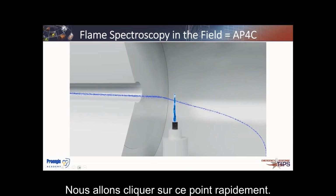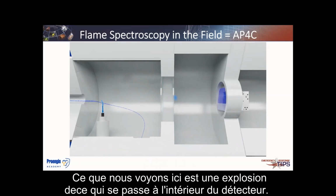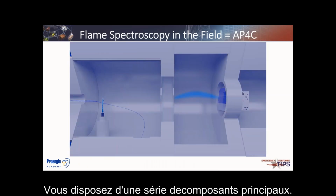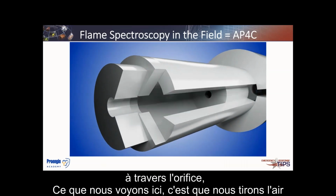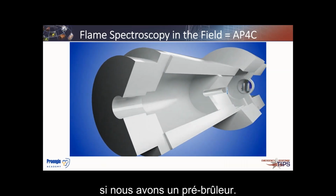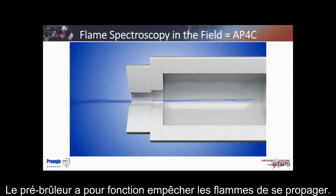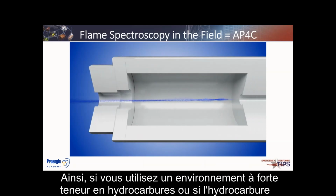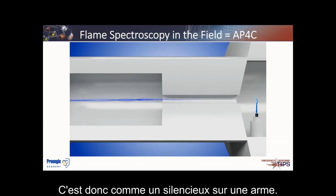So we'll click on this real quick. What we see here is a blow-away of what's going on inside the detector. You have a series of main components. We're pulling the air through the orifice, and we have a pre-burner. What the pre-burner does is help prevent flames from propagating. In the event that you're using a high hydrocarbon environment, or hydrocarbons are present, you're helping prevent that. It's kind of like a silencer on a weapon.